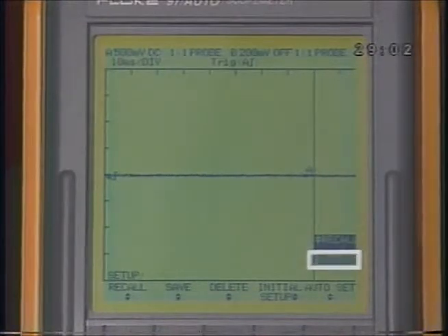Check the right menu. Look for a flashing cursor. It should say No Trig, telling you Scopemeter's ready and waiting for a signal. If it says Hold, press Hold Run. The highlight should change to No Trig.